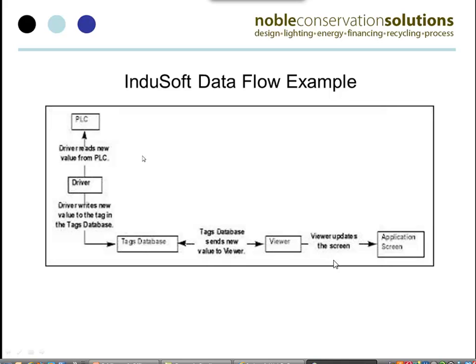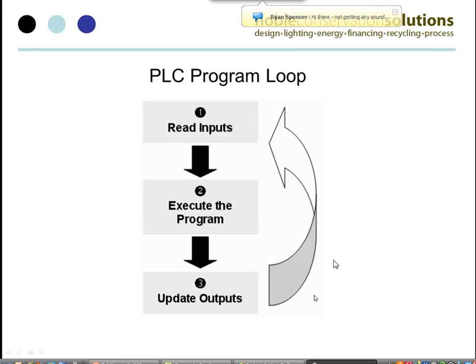And we also provide the opportunity to change variables. By changing variables, that means we can control how the units are working within the building, so we can change settings. And by changing settings, not only do we have visibility, but we have control. With control, we can create change based on what we see in our trending and have positive influence with that without physically having to be there, which is obviously a big cost savings and an issue with regards to control.